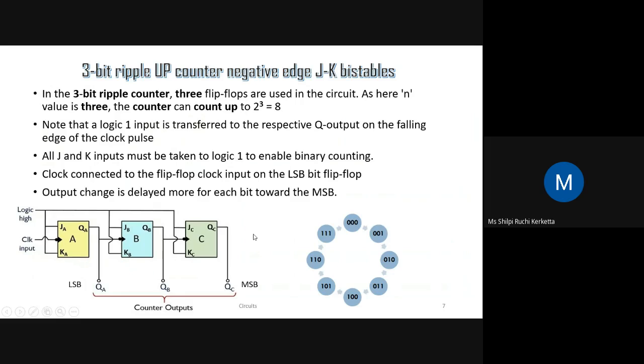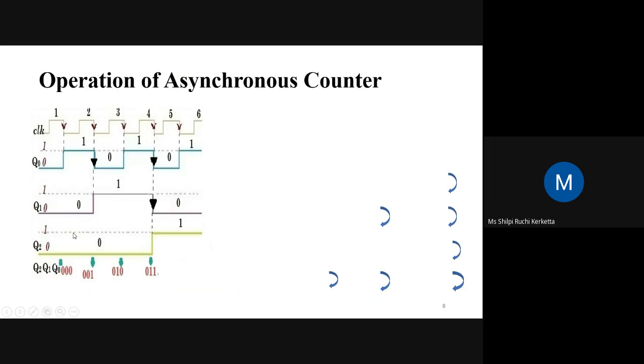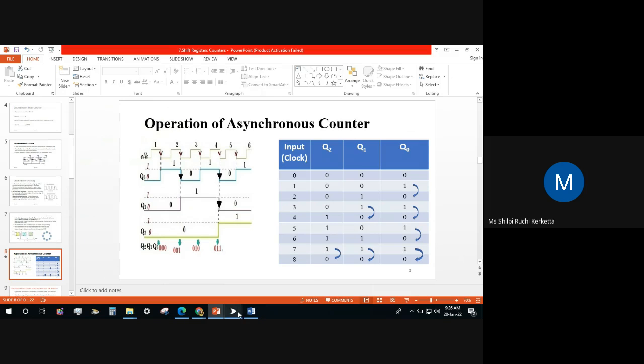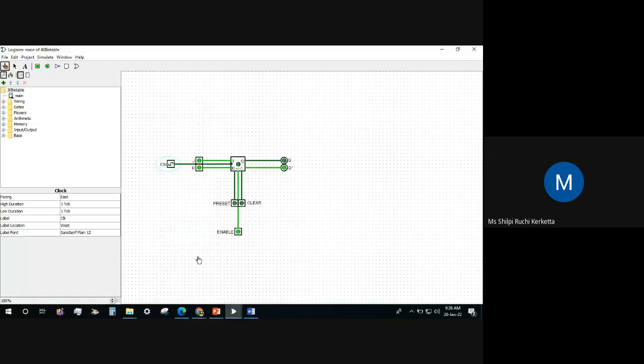So here in this flip flop, what it is doing is delaying our clock. Here we saw the JK flip flop. Whenever J and K are 1 1 and we are changing this, with positive edge triggering, if we give a 1, it is totally changing. It is flipping. So we are using this part. Whenever there is a positive edge, whenever we give a 1, it is changing. That's why we are using this JK flip flop.